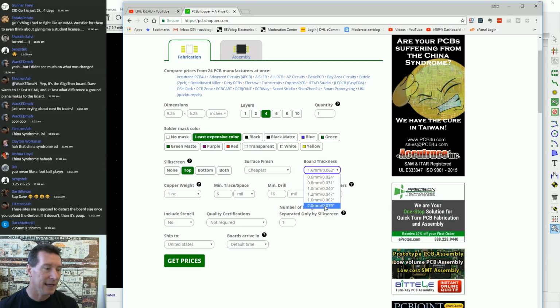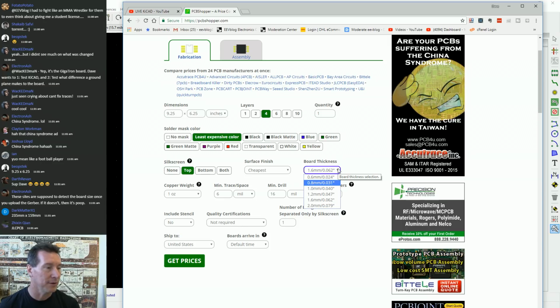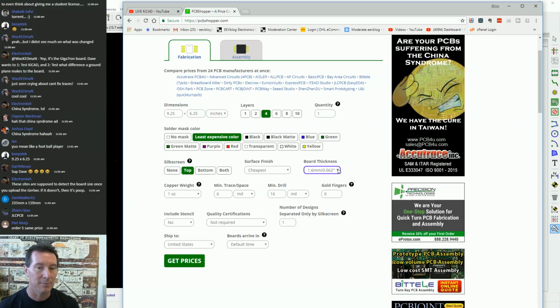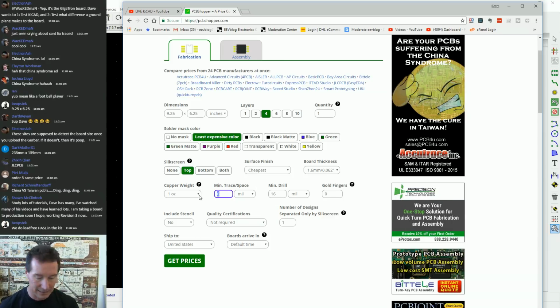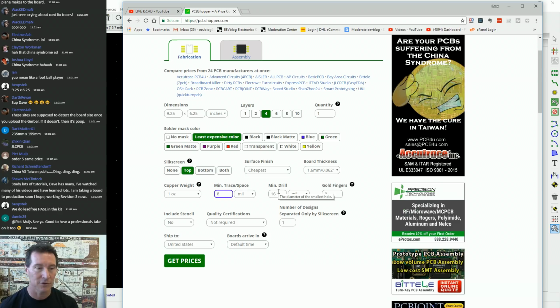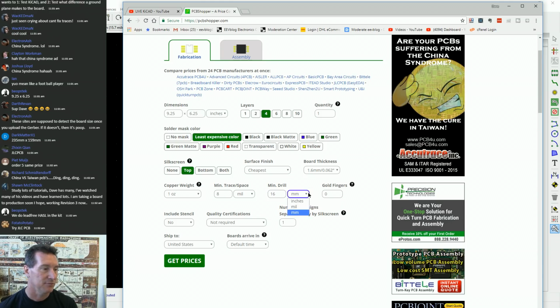2 mil. Oh, really? You can't even go above, you can't go to 2.4 or anything. You can't do any thickety doodad boards. It's a shame. 1 ounce copper. 6 mil trace and space. I think we're 10 mil, like 10 thou or something, but I'll just leave it by default. Whatever. I don't know what the design rule in this one was. Minimum drill size. No one does drill size in inches. Rubbish. Anyway, I'll just leave it by default.